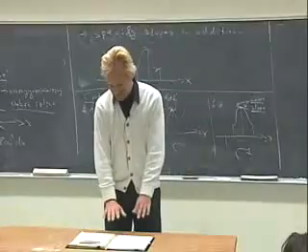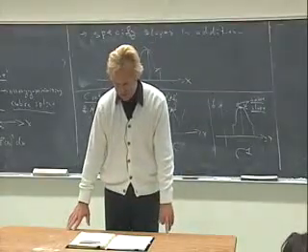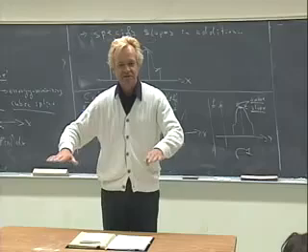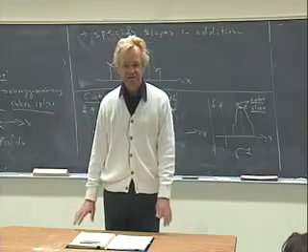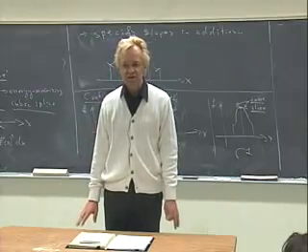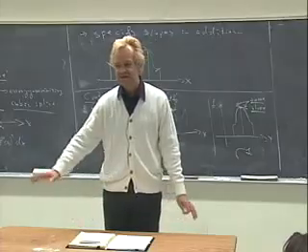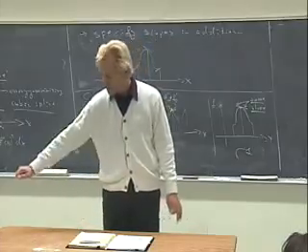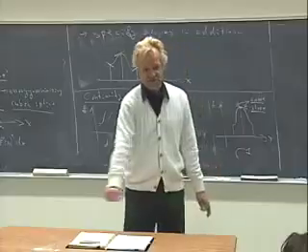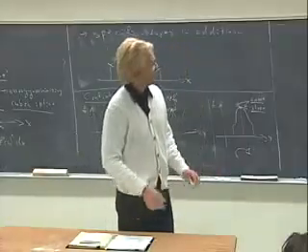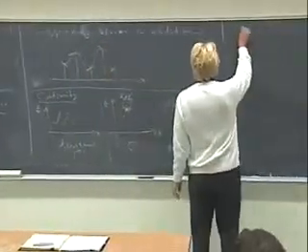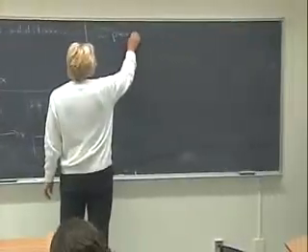So if I have a definition of a geometry, I need also a definition of an offset. Very important for many applications. Also for numerical machining, whenever you're milling something, the milling machine has to run in parallel to the object that you actually want to mill. Okay? So that's why these operations are very important.